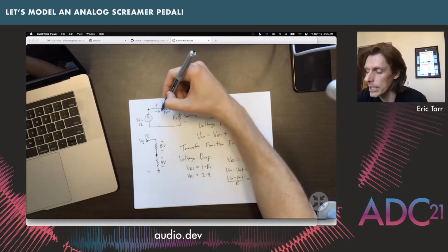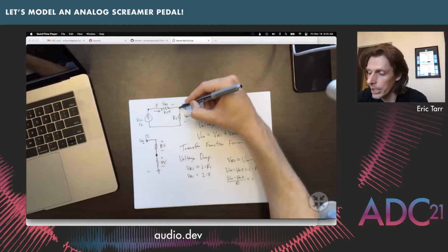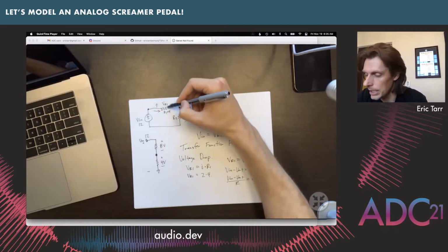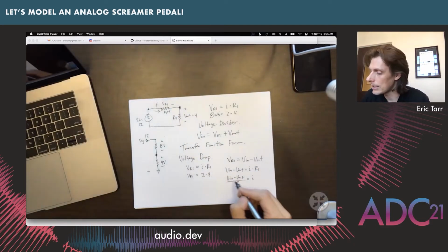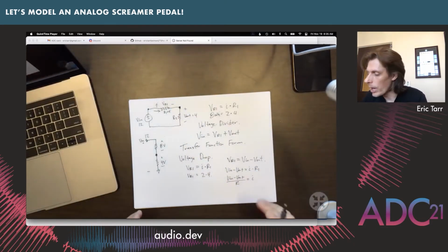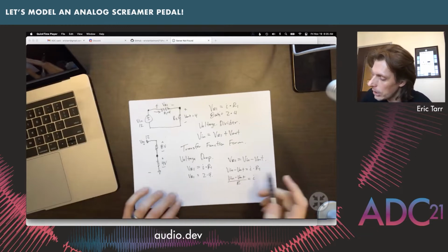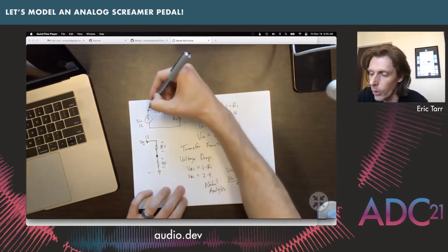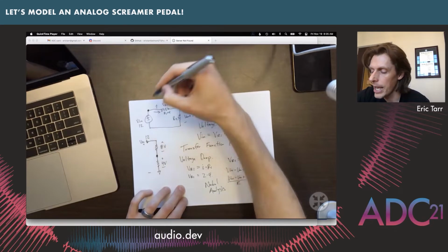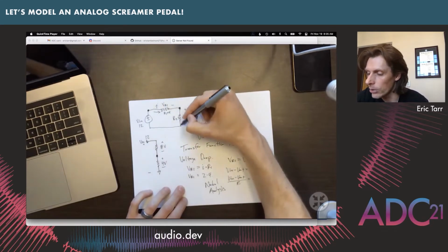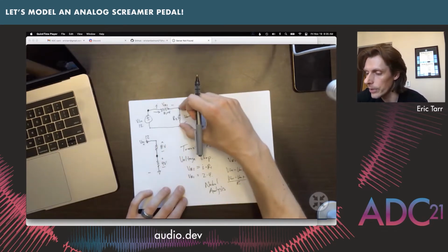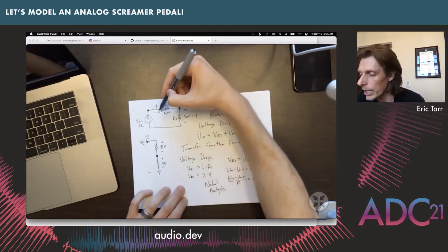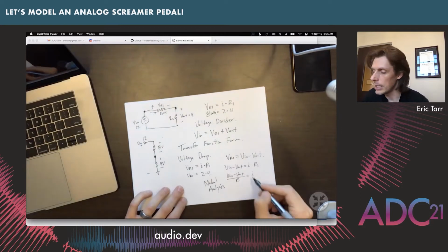We have the current flowing this way, minus the point over here divided by this resistor is equal to that current. So that's a very special way to do it that we'll use as part of this technique called nodal analysis, where we define these different points and call this one V in. We have this one over here that's called V out. These are the 2 nodes that we want to use. And so we can determine our current here going in this way by using this relationship.